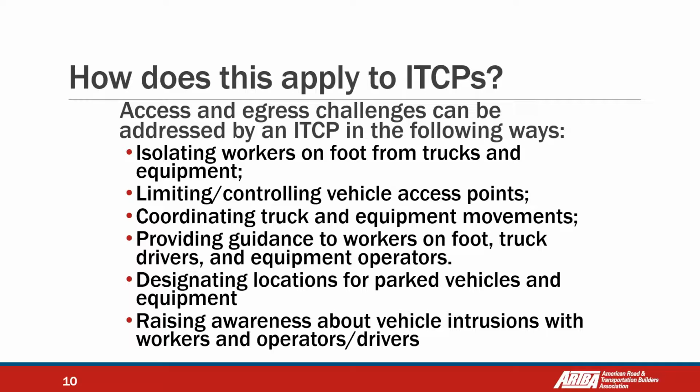Then providing guidance to workers on foot, truck drivers, and equipment operators. It is important for the internal traffic control plan to communicate to everybody, all the stakeholders involved in the work zone, what the plan is. So knowledge is important. If people know what to expect in a work zone, where is the access zone, where is the parking area, where is the waiting area or the truck lane areas to wait for delivering materials, it is going to help a lot everybody to do their job safely.